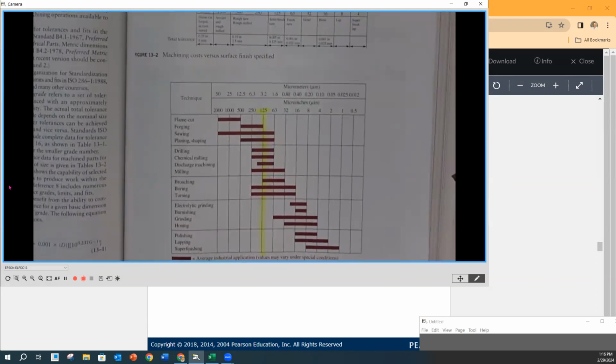So this is probably going to be a turned part, right? Picture this mandrel. Within the turning range, you could go from 250 to 16. So in your case, if you need a little smoother finish, you don't want something to catch on that, then you could tolerance a 32 finish. And they could still most likely turn it, so you're not introducing a more expensive process like grinding.